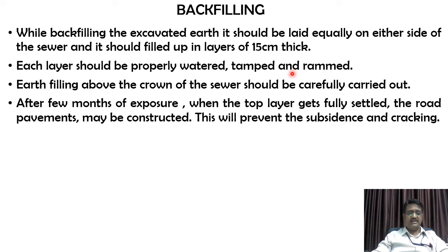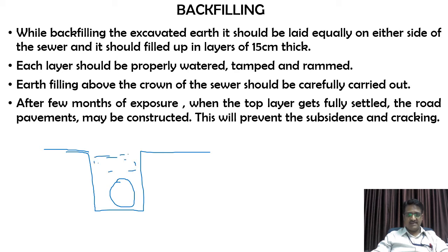The reason behind this is that right now, after construction of a new road, you might see that roads sometimes cave in. The reason behind that is, imagine this is a trench, a section of that. Here we have laid that pipe, and on top of that we have put the backfilling.